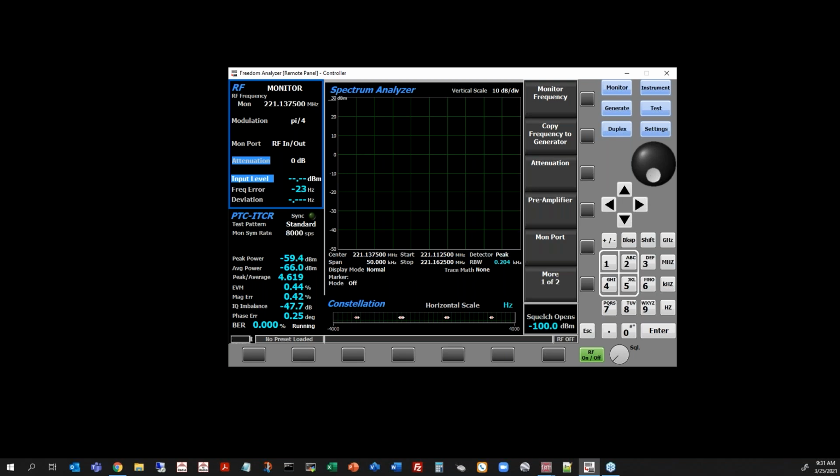Let me get on the one screen. So I'm going to take my radio and I'm going to do a wayside radio, which is the same as what the picture was in the presentation that you guys have seen. So this is a half rate carrier, and a wayside can only transmit in half rate. And I want to preface this with, I have about 4 dB of attenuation between the monitor and the radio. It's just a really super long cable that I had to use, so I've got some attenuation there.